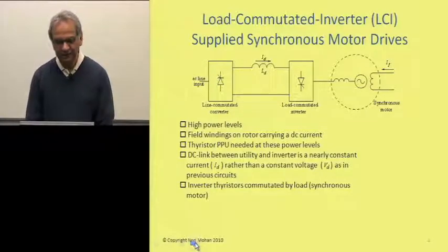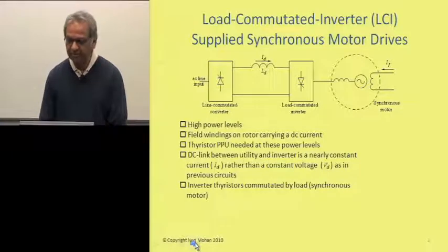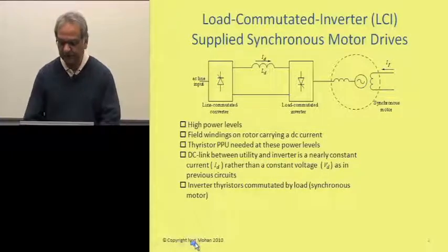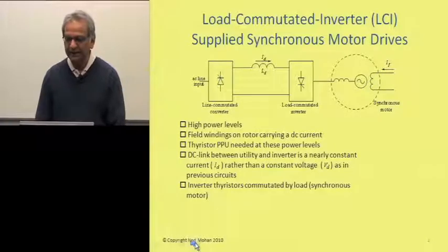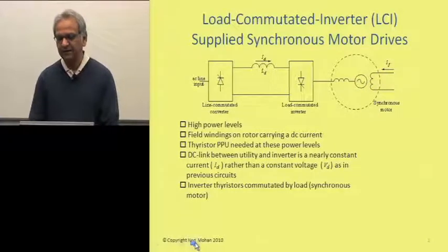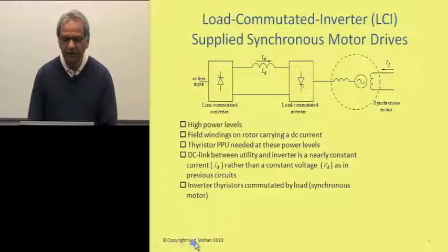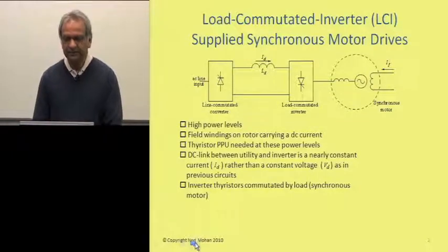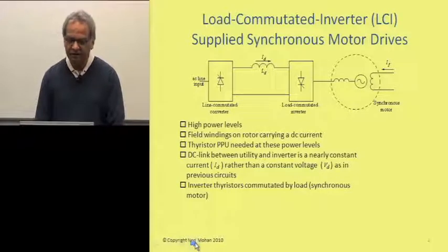So that's the field current I sub F that is being supplied to the rotor windings, producing north and south poles. And then on the stator, we have three-phase windings, and these three-phase windings are supplied appropriate currents, but through a thyristor-based converter arrangement, as shown here.